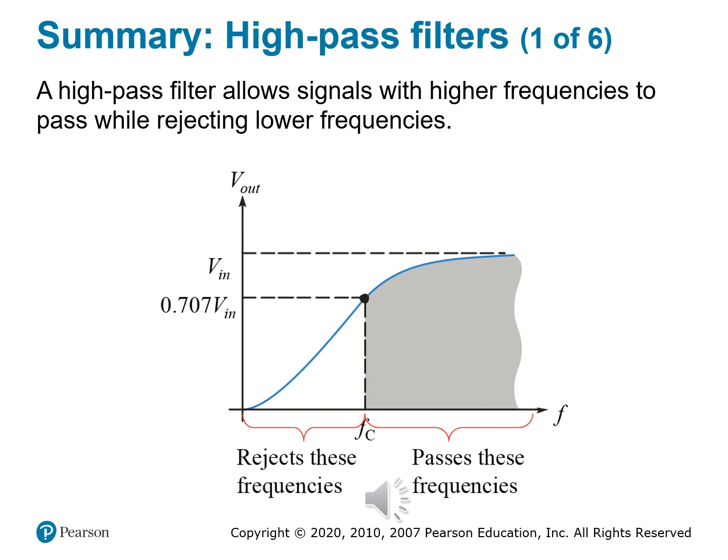And let's talk about cutoff in action. That cutoff point, 0.707 times the input voltage, or remember, it's also the negative 3 dB point. It isn't just a line on the graph, it's a design target. That's where we define the boundary between reject and pass. So again, know your boundaries. To the left of it, we have frequencies that are rejected. To the right, frequencies that are passed. And it's all about shaping your signal for whatever task you have at hand.